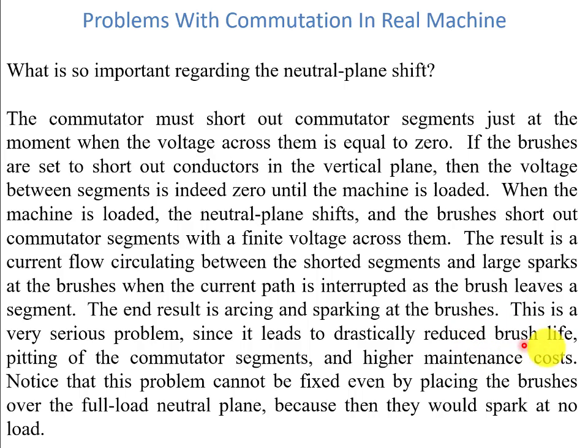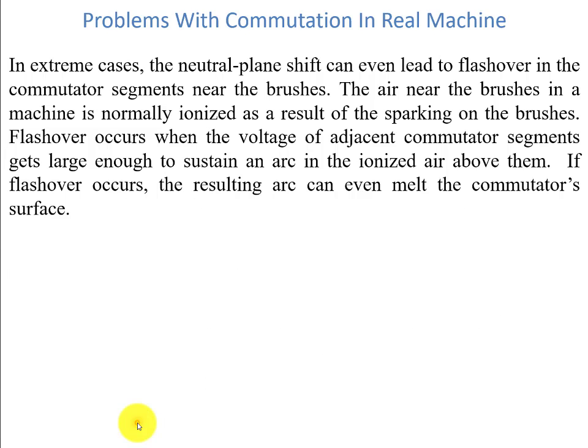Obviously when the brushes wear out, they also produce some powder-like material in the machine, so we have to clean the machine more often. There is also pitting of the commutator segments and higher maintenance costs. Notice that this problem cannot be fixed even by placing the brushes over the full load neutral plane, because then they would spark at no load. So this is one of the big problems.